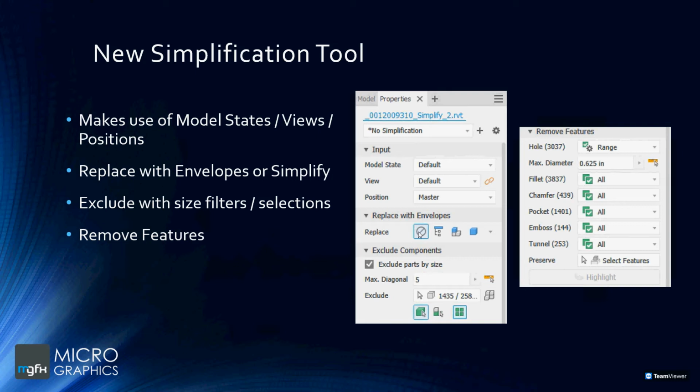The other option here is to also replace each top level assembly or part with its own envelope. So if you have 10 machines or 10 sub-assemblies in your Inventor, you would end up with 10 bounding boxes representing the positions of those items. So essentially, like I said, you're creating these bounding boxes to represent the space requirements and reducing the amount of intellectual property as well that you might be sharing. You may not want to share a detailed version of your design. So you just give a bounding box and say, okay, that's where my machine needs to fit.